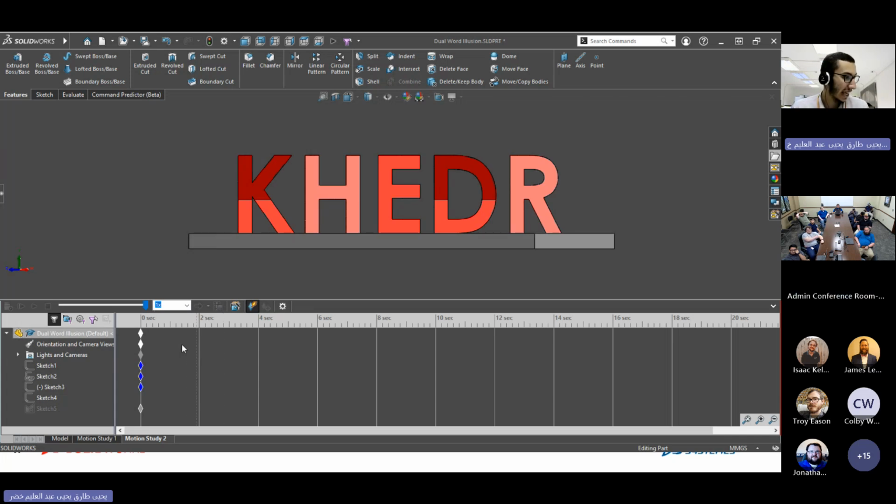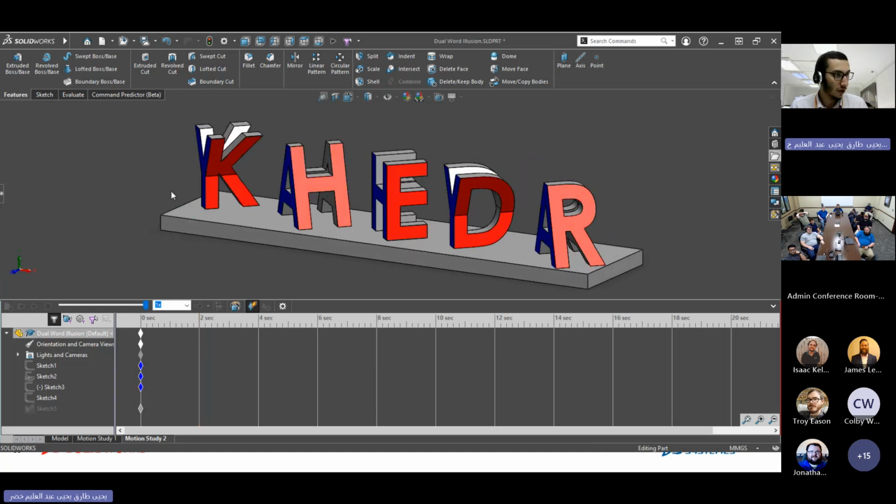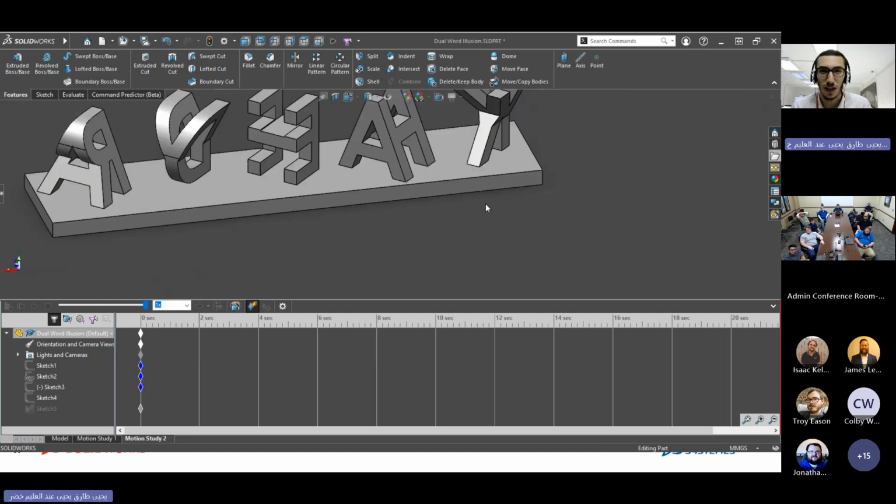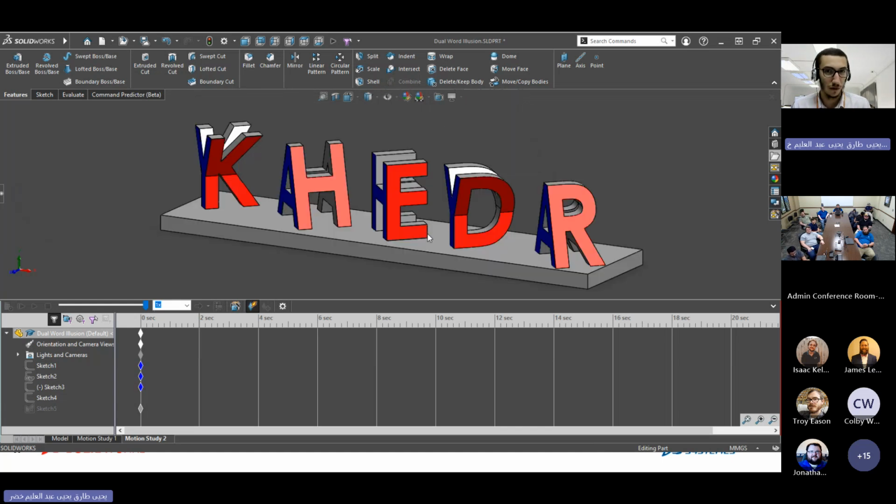Except that I don't see any camera key points or anything added. And that's actually by design. So the thing is, usually you don't have everything that you need in your animation previewed to you in that still frame that you're starting the animation with. You might need to select a face from back there, so you might need to rotate, maybe zoom in, zoom out, stuff like that. So you don't want SolidWorks animations to automatically capture all of these movements. Sometimes you would need it to, hey, just take a second, only save the view keys when I tell you to. Only view keys. Any other movement, that's probably going to be intentional. But when it comes to view manipulation, it's usually not going to always be for the animation.